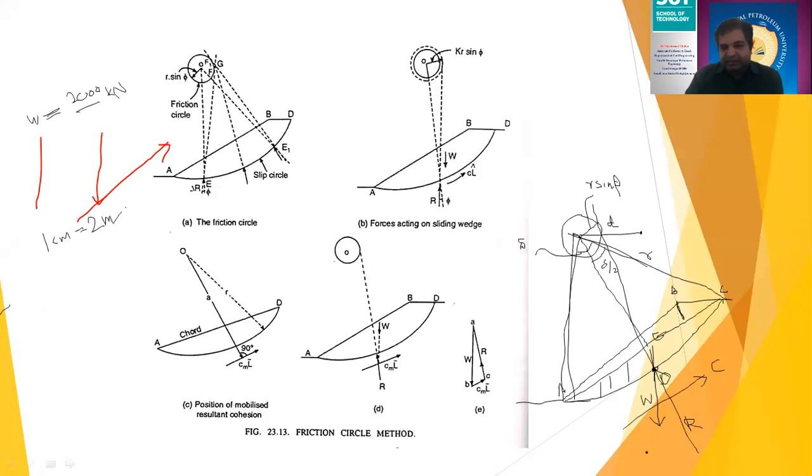And then the reaction, which is parallel to this R line. So the reaction I'm going to draw from this line. This will cut this particular line in this direction. So you will get the direction of C. So you can get this length, multiplied by whatever the scale value, and you will get the value of C here. At the same time, you can get the value of R here, which is in this direction. Now, once you calculate the value of C here, this is a cohesion.